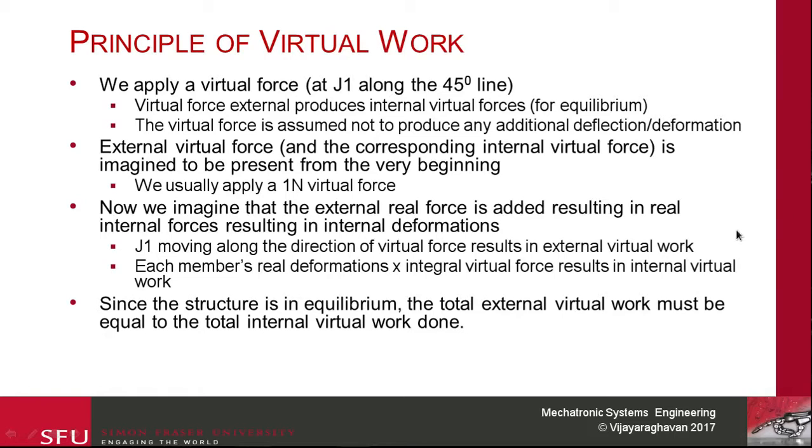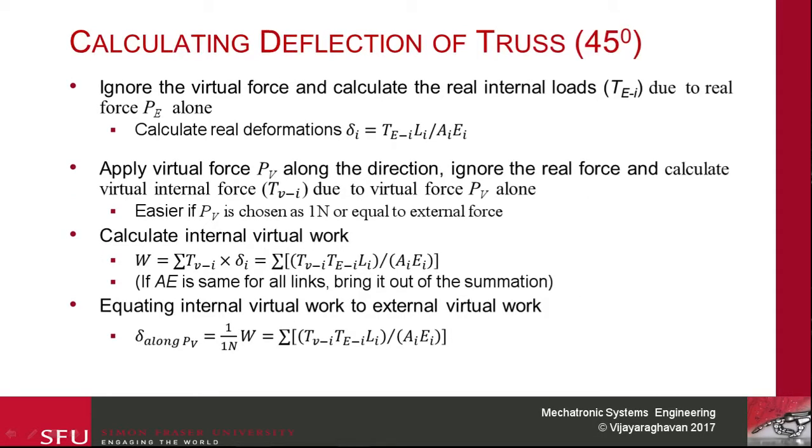Basically, the external virtual work and the internal virtual work, and then we can solve for the displacement, because the only thing that's going to be unknown is the real external deformation. So the real external deformation is the only thing that's unknown in this equation. So let's see how this is done in practice.